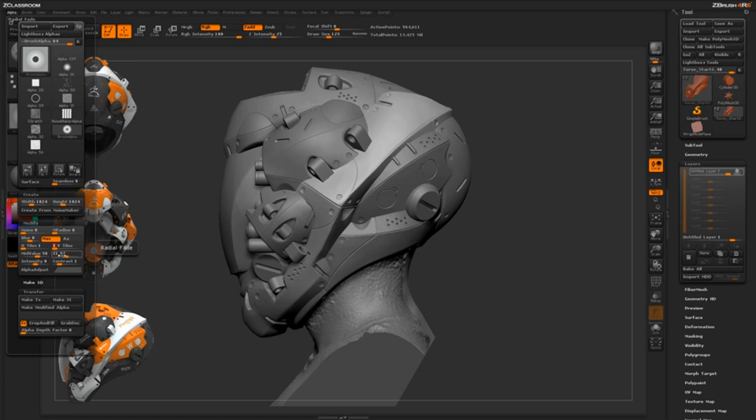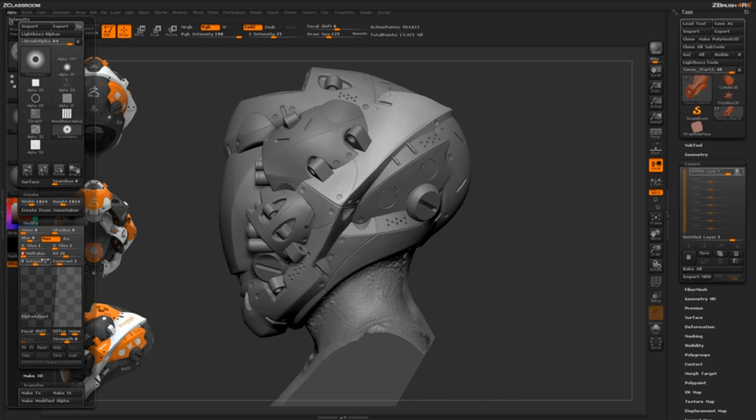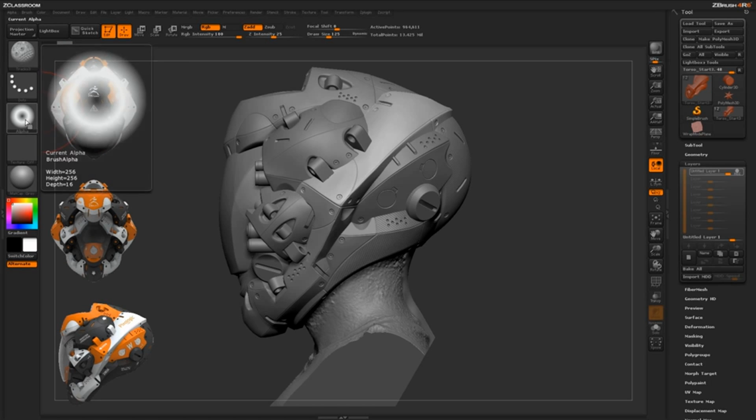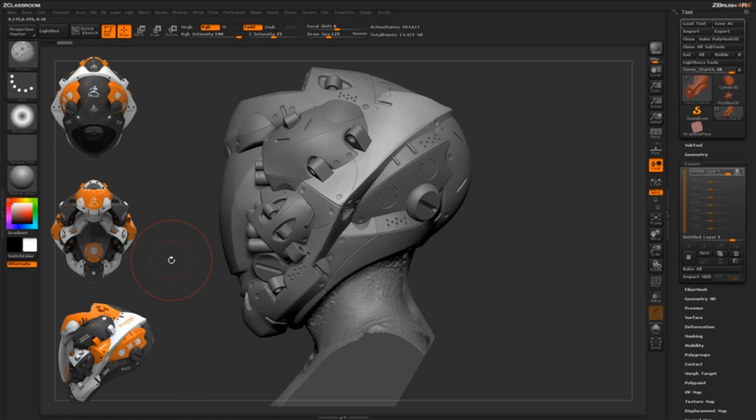So it has a mid value, a radial fade, and then the actual alpha graph is adjusted as well. So we just need to go ahead and reset all these. I'm going to change the mid value to 0, radial fade to 0, and then for the graph I'm going to come down here and just click reset. So now all this stuff should be reset, and the brush is now ready to take one of the alphas that we've generated and apply it across the surface.